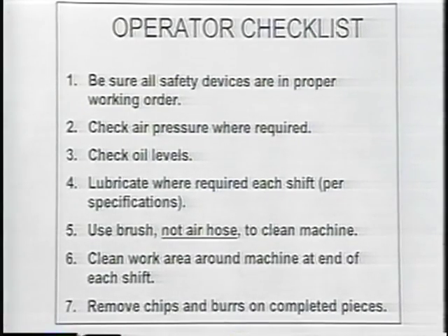You notice the first thing is safety. Check the safety devices. And then there are some gauges that have to be reviewed. In this case, it's the air pressure. We may look at an oil level on a gauge, or we may have the old-fashioned dipstick to go into an oil reservoir.